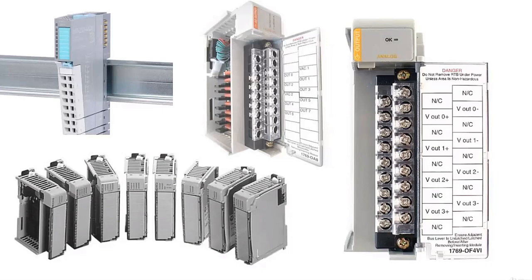And you can take that PLC and drop it right into a project, load it with a program, and you're ready to go. But when you buy the more sophisticated PLCs, they typically come with no I/O whatsoever, and you have to add on modules in order to receive signals or send signals out.